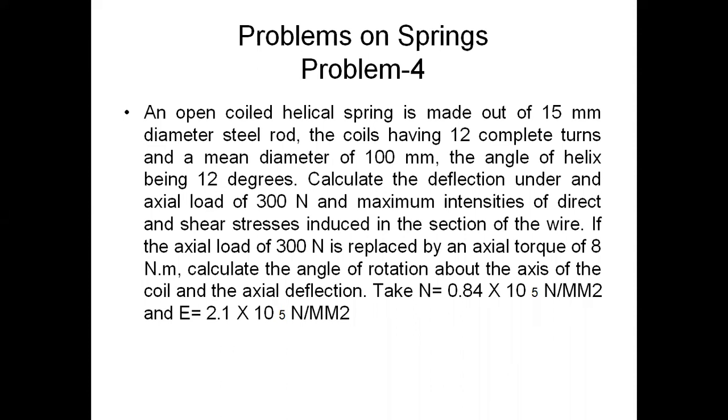How much? 10 degrees. Very good. 10 degrees. So as it is 12 degrees, will it be open coiled or closed coil? Open coil, sir. Very good. So that's very clear. So that's the reason why the angle of helix was given as 12 degrees. Sorry, 12 degrees, not centigrade.